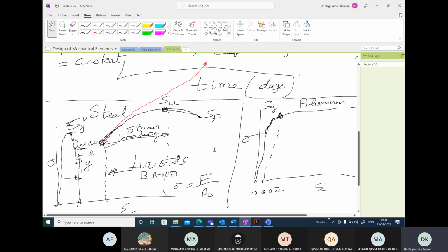Okay, so this is the stress strain graph. We have extracted all required properties. We have the yield strength, ultimate tensile strength, fracture strength, and then we can also extract, up till the proportional limit here, Young's modulus. So initially we have a linear elastic response, and from that we can extract the property called Young's modulus, and also for aluminum we can extract it.